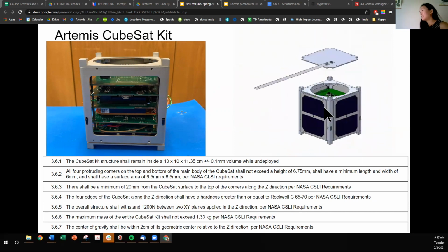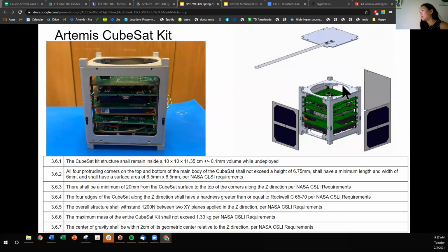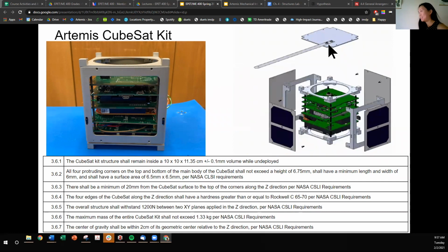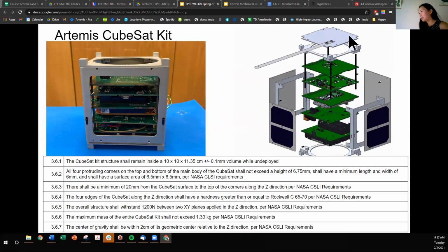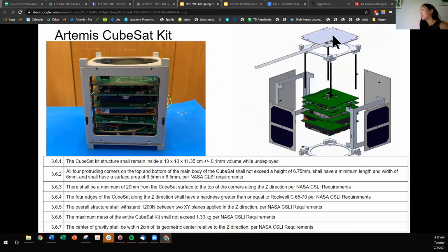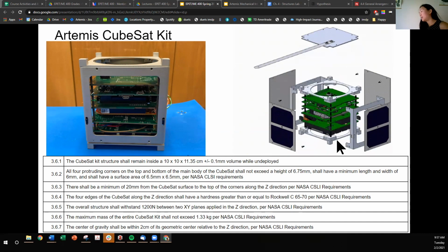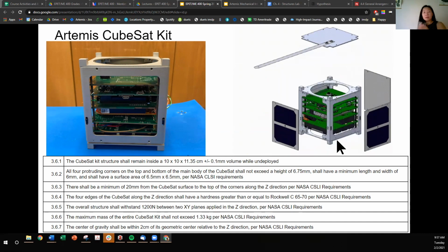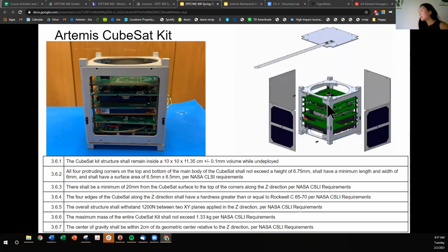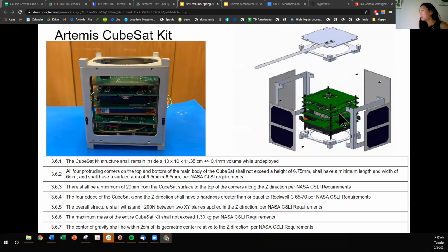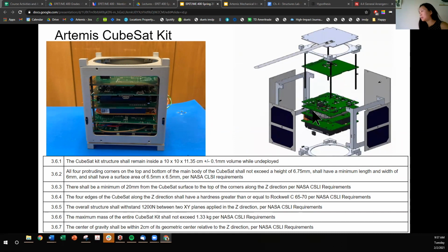I think this diagram is not reflective or representative of a good mission, because that view is occluded by this panel with the antenna. So I think really this antenna should be on the bottom face. Let's see, there are electronics that are buried in the center, especially the onboard computer.